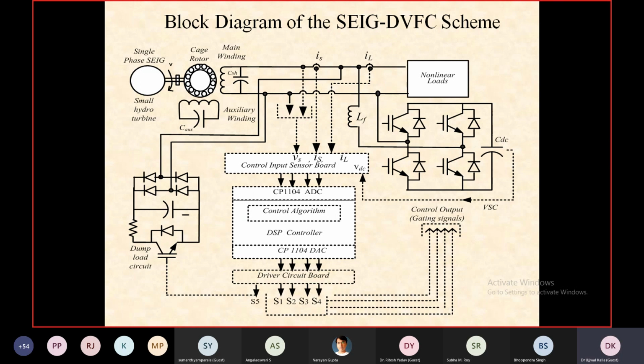But here we have connected a big size capacitor at the output of the rectifier. That is not advisable. But if you remove this capacitor, you have to have all the 4 diodes of high frequency.